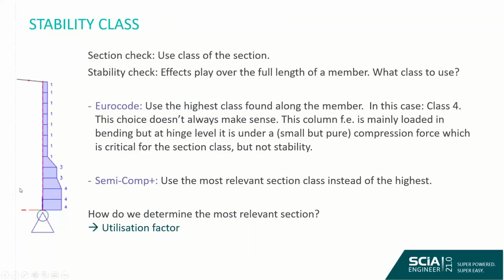But if we look at this column, for example, actually, let's say that there's a lot of wind, but not a lot of vertical loads. This means that the highest loads will be the moments at the top of this column, whereas at the bottom, yes, we have some compression, but this will not reach the full capacity of this column, and it will mostly be designed on the bending at the top. So there's a lot of room left at the bottom of the column.